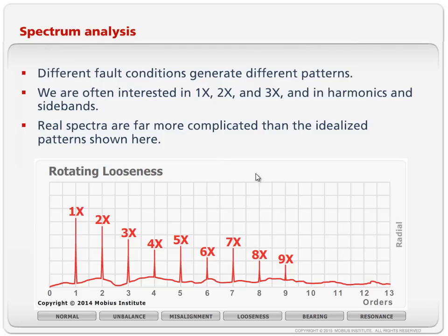So, lots of different patterns. But one of the keys is not to get locked into trying to remember patterns. Don't be a wall chart analyst that looks at a spectrum and then looks up at the wall chart and says, that spectrum looks like this sort of fault. What you need to do, in my humble opinion, is become one with the machine. Think about your machines. Think about their failure modes. Think about the technologies that will detect those failure modes. Think about how you should take your vibration readings and where you should take your measurements and so on.